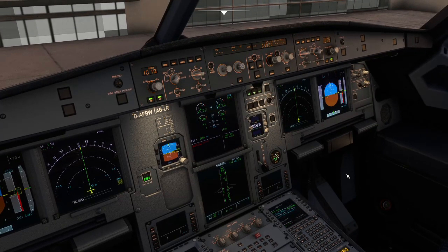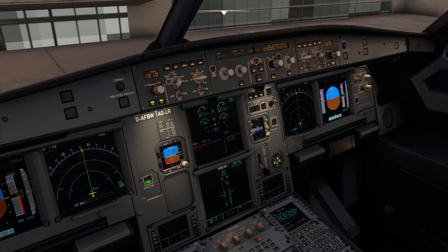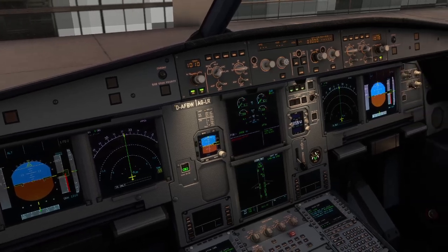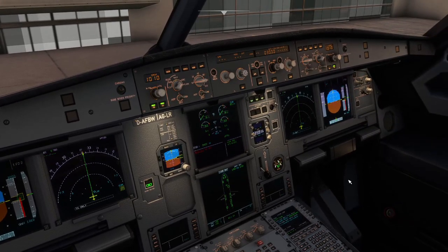Only thing you could do on that approach, you could have gone dual autopilot, and it would help out with the final bits and the flare and the landing. It was fine single autopilot for an autoland. Would have been even nicer with both autopilots in. The whole goal there was to show you a startup to shutdown landing with the jet basically doing its own thing. Very minimal things I had to do other than the rotate on departure, keep it straight, and then the decel and the braking on the landing. Don't pay too much attention to the taxiing. We can all go practice taxiing in our own time.